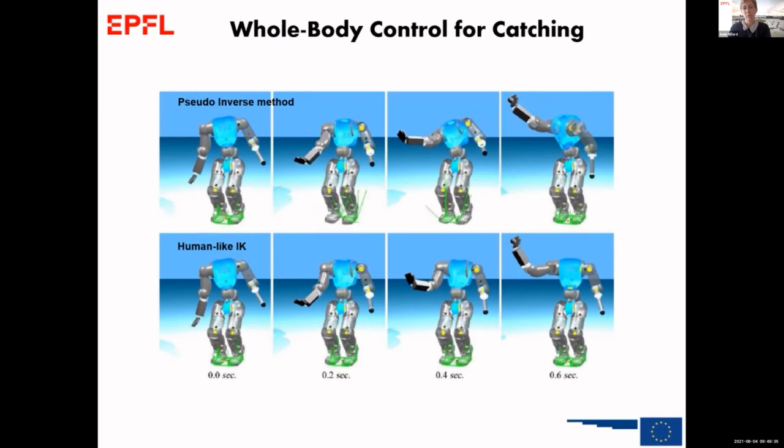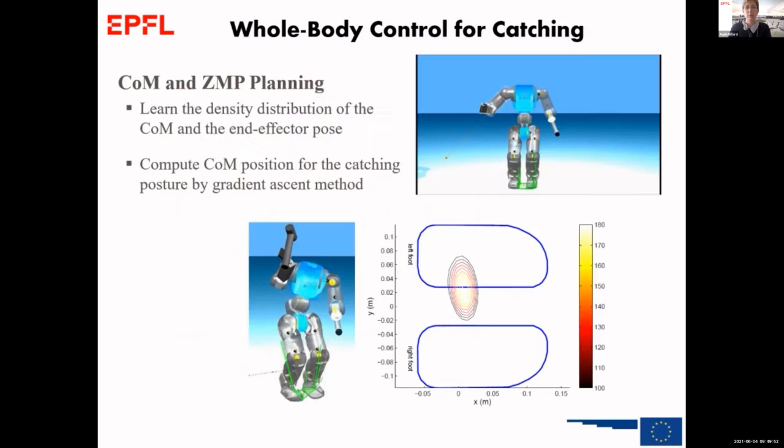And so you want to be as close as possible to those joint trajectories. And in fact, it gives you much better results, especially results that are closer to things that are stable. So you still have to stabilize after that, but at least you're less far away from stability.